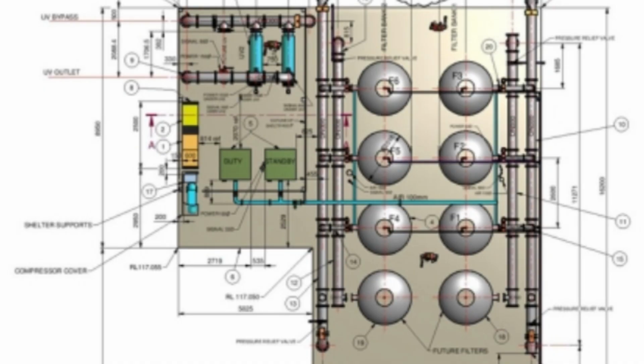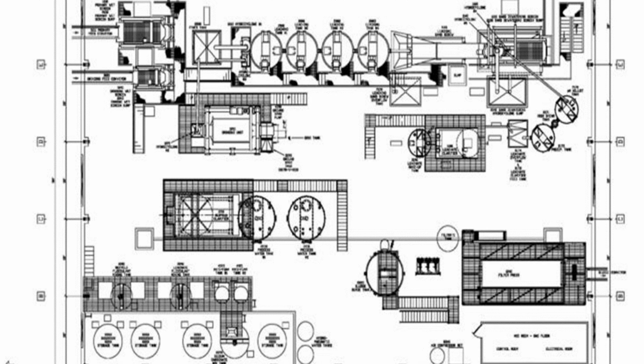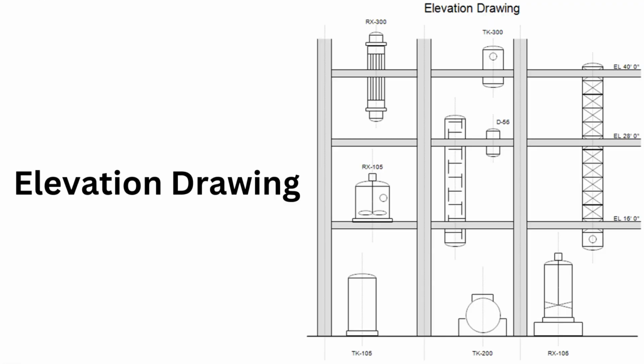Next is the two-dimensional layout. Two-dimensional scaled templates are prepared either for the entire plant or for individual units. It gives more details for the space utilization. On the plant layout, details of individual equipment, buildings, storage, utilities etc. are mentioned. Two-dimensional elevation plant layouts are also prepared.